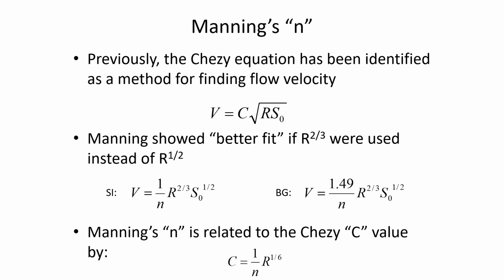So in other words, when we have Manning's equation, we'll commonly say it is the area to the 5/3 power, slope to the 1/2 power, divided by n times the wetted perimeter to the 2/3 power. So that will give us Q. This is just another representation of the same thing. Of course, as I've written it on the board, it would be for SI units.